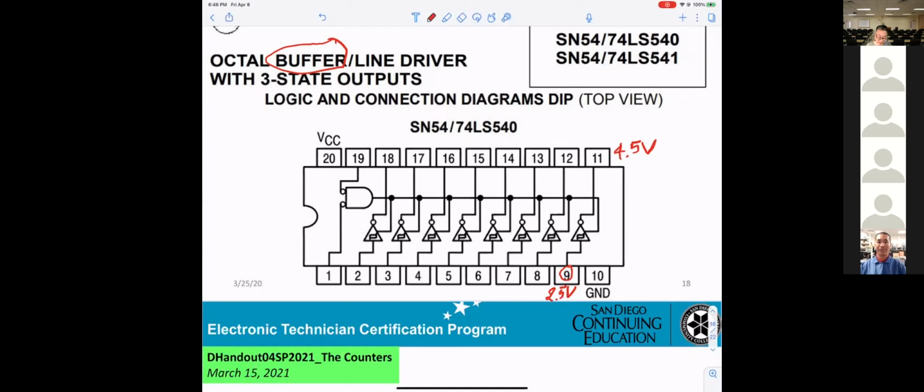I give you another example. 0.5 volt here. What logic? 0. However, when it goes to pin 16, you get 0.1. You see that? Binary, they want logic 0 to be 0 volt. That means close to 0, much better. Our logic 1 is 5 volt. Close to 5 volt, that's much better. So that's why they need a buffer.